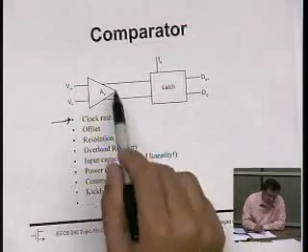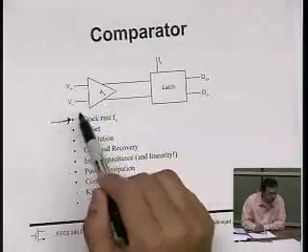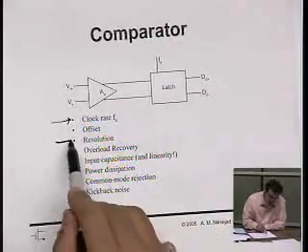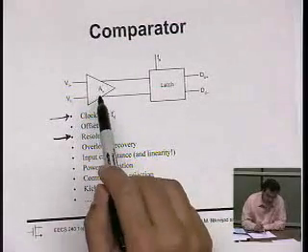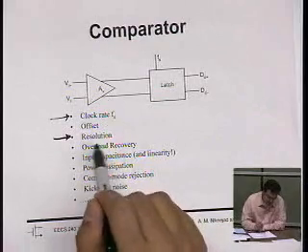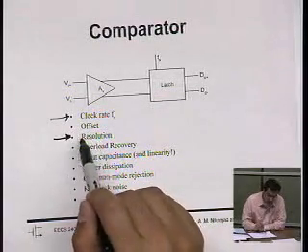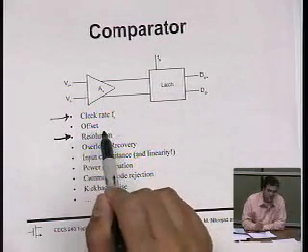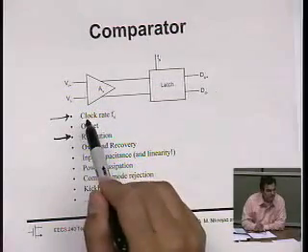The offset voltage determines the minimum signal that I can detect. It really determines the resolution. So together with the gain, if I design a good system, my resolution should be determined by the gain. At some point, though, if I put too much gain in my system, then I'm overdoing it, because I'm going to just be limited by offset.